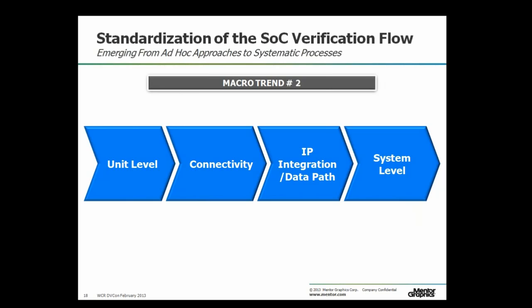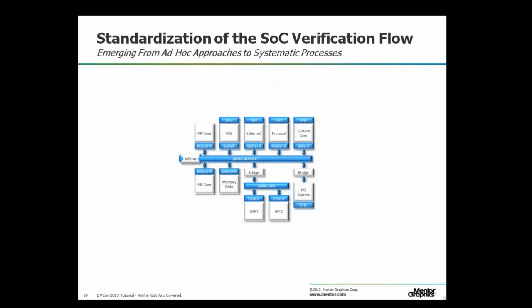The second macro trend that we're seeing is that we are starting to move from a well-defined process and verification for IP and IP blocks to a well-defined process for SoC, starting with unit level verification, connectivity, integration, and system level. So here's what we mean by this. If we look at a trivialized picture of a SoC, we're pretty common with the concept of block level verification, achieving coverage as fast as we can, a test under all conditions, interface-centric technology. So we verify each one of these processors.